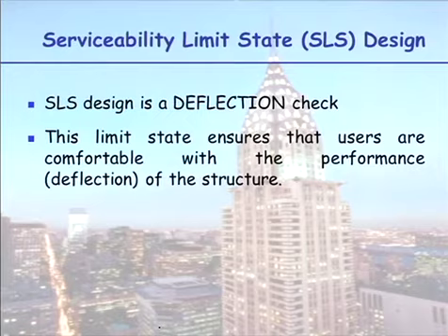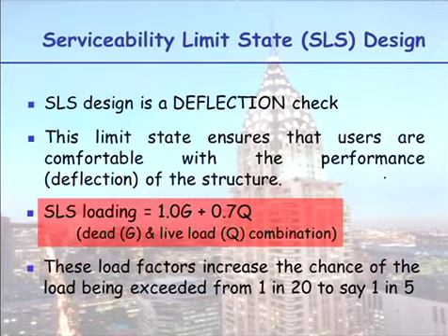We also design for serviceability limit state design. That is to design so something doesn't deflect too much, so the structure is serviceable. So as well as in that, when you design a sports floor, you have to ensure it doesn't vibrate too much as well. So the limit state that ensures that users are comfortable with the performance deflection of the structure. So we use the same loading, we put different load factors on. So we assume we have the dead load, and now we actually take only 70% of the live load. And what we do is we then say, with that loading, how much does it deflect? Okay, it's less than what it has to be. So there's some upper limit, and we say it's less than what it has to be.